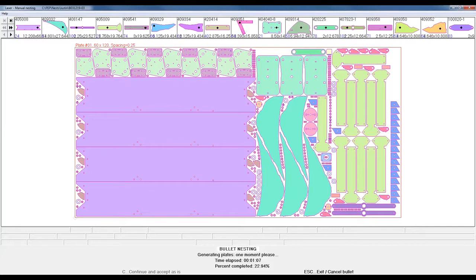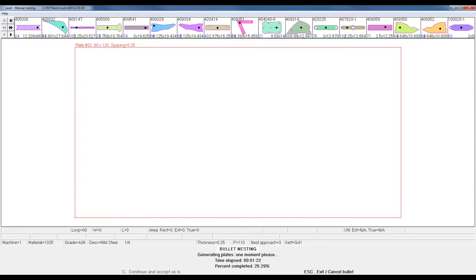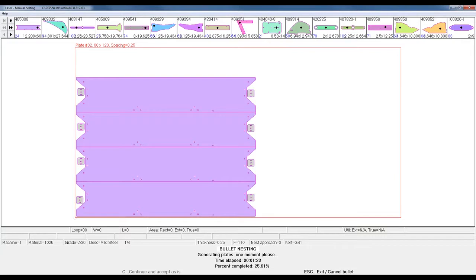That means you won't have to take the time to common line cut these yourself, as can be the case with some other software, where it's quite troublesome to do. But not only that, you're going to get the nesting utilization for it as well. So it's going to know your common line cutting, and it's going to nest around that. You won't have to change the nest manually.